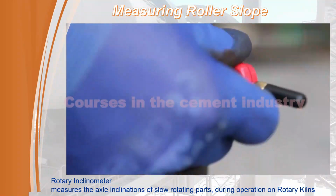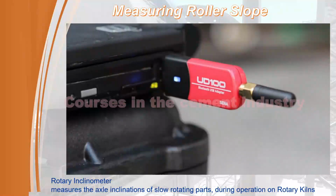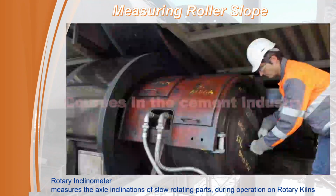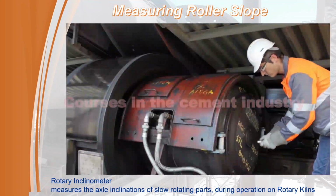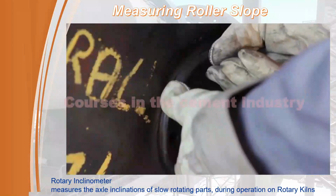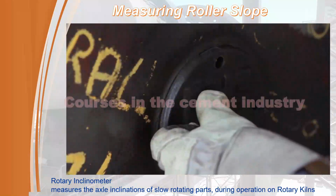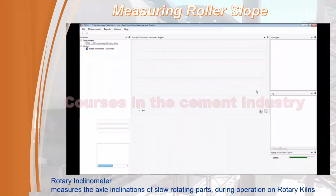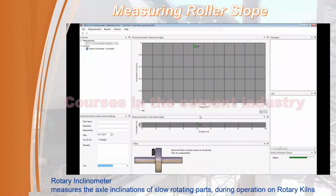As a first step, the Bluetooth adapter has to be plugged into the laptop. To connect a tool, select it and click on the connect button. In order to perform the measurements, the roller shaft has to be accessed. When opening the cover, ensure to use proper tools and prevent any contamination of the bearing. Now, the inclination sensor, which is the main sensor, has to be calibrated on a rotating part.